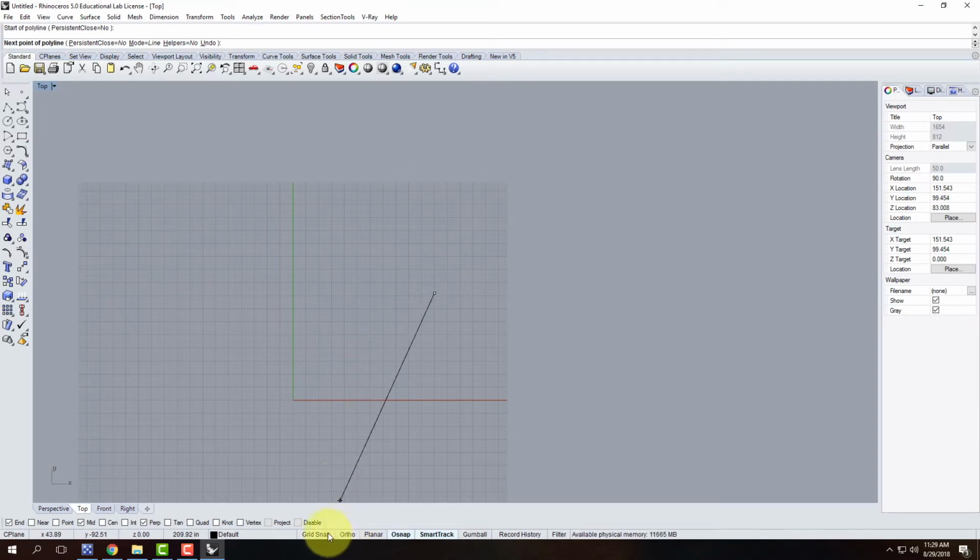I'm going to turn on down here at the bottom, and I apologize if you can't see it, what says ortho on it. And when I have ortho turned on, you see that it's going to lock me into drawing just at 90 degrees. So I'm not off at an angle. Now, all I have to do is to type in the length of the line that I wanted, and then click in the direction that I want it to go.